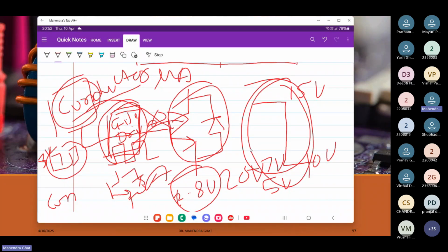So you have to check in the data sheet what the threshold voltage is and what the current requirement is. And then you see whether your gate pulse generation is able to give that much voltage level and current.